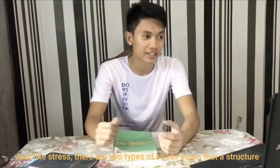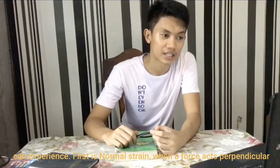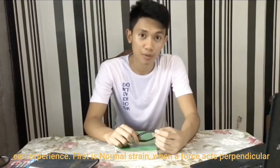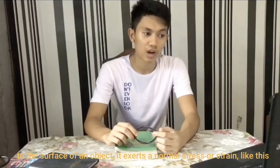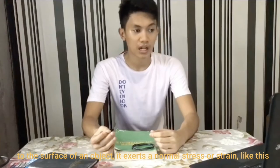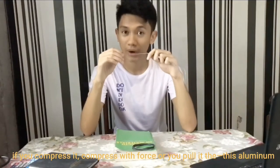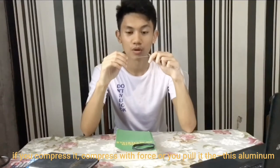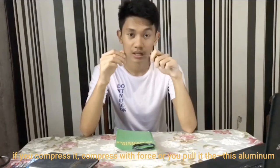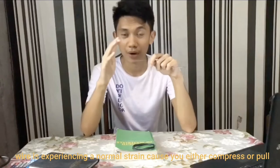Just like stress, there are two types of strain that a structure can experience. First is normal strain. When a force acts perpendicular to the surface of an object, it exerts a normal stress or strain. Like this. If you compress it, compressive force, or you pull it, this aluminum wire is experiencing normal strain because you either compress or pull.